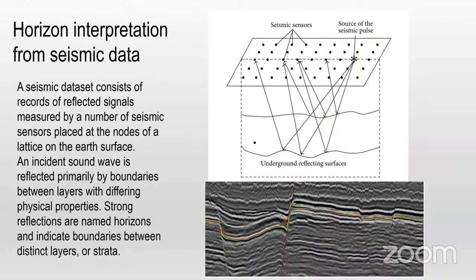For exploration, mostly you have 2D seismic data because it is less expensive than 3D seismic data, and it gives you very limited data from the horizon. It gives you the type of horizon, but for example, for the faults, fault lines, and fault displacement, it does not have good quality.